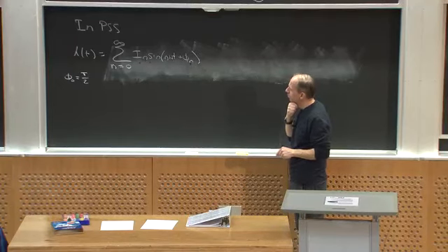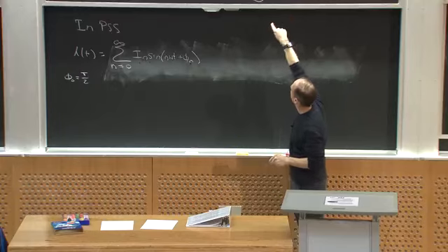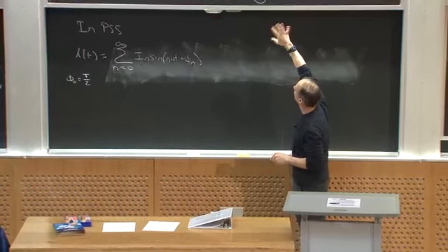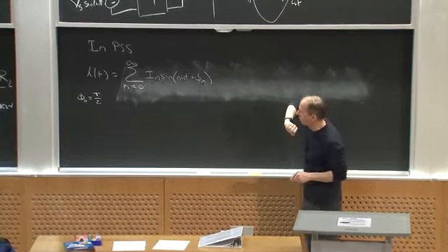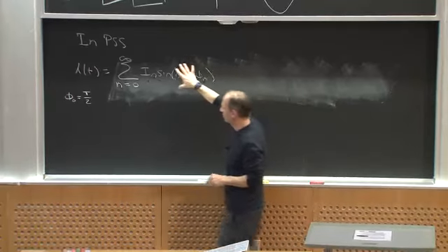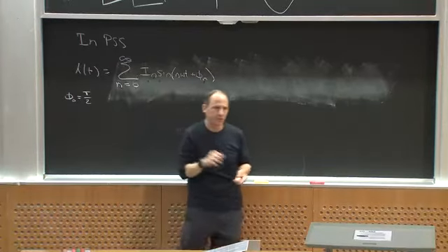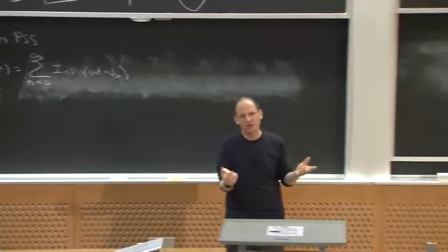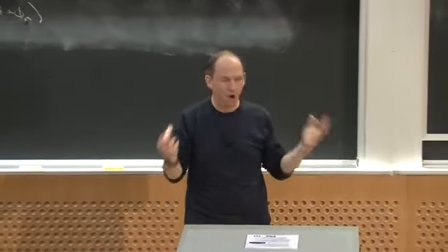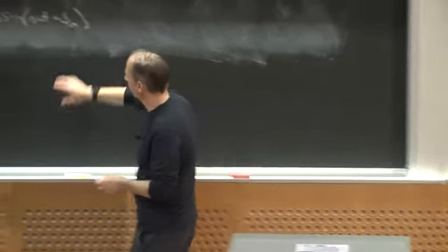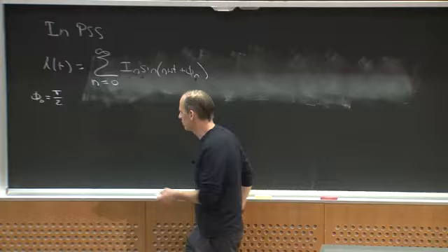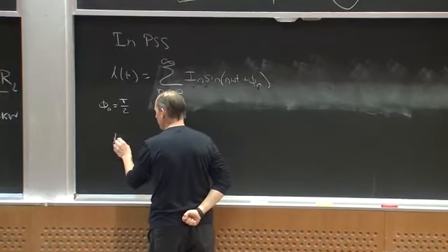Okay. Well, so I can represent this pink waveform, or any other AC waveform that's not sinusoidal, as long as it's periodic, with some Fourier series. Okay? You can relatively easily show what the RMS of that waveform is. If I break it down with this Fourier series, we could write RMS as follows.